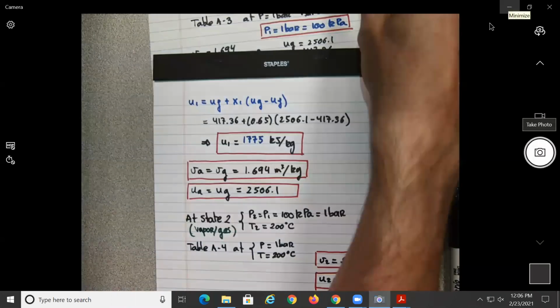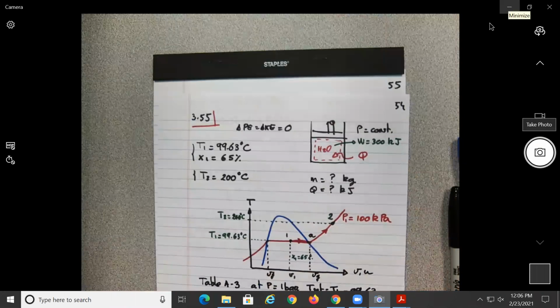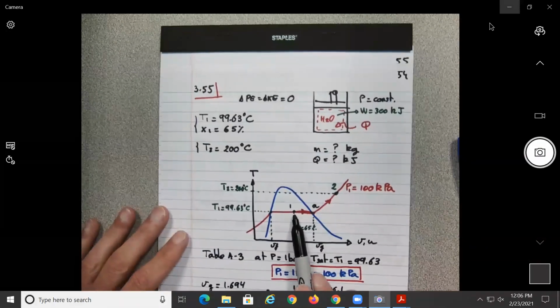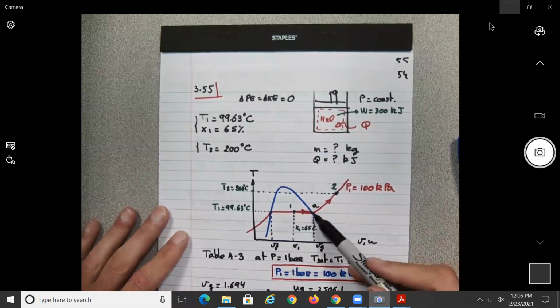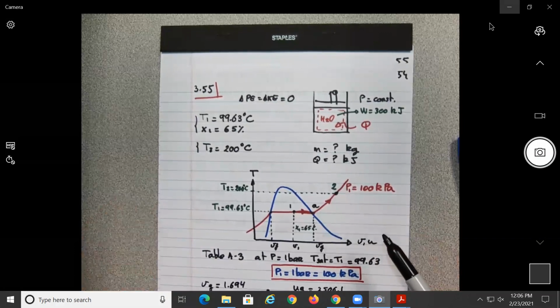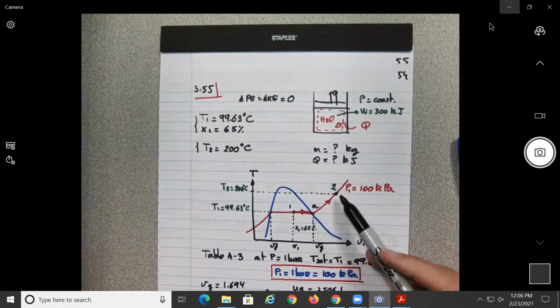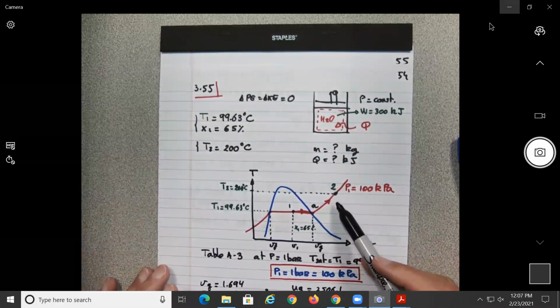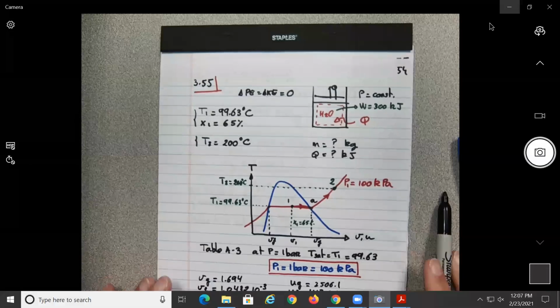All right, so basically right now, the total work done during this process will be equal to what? To the work done between 1 and A, which will be at constant pressure, no? And then here between A and 1, so this is a good question. I guess they assume this will be a linear relation, or they're just going to assume PV equal to constant on this one.